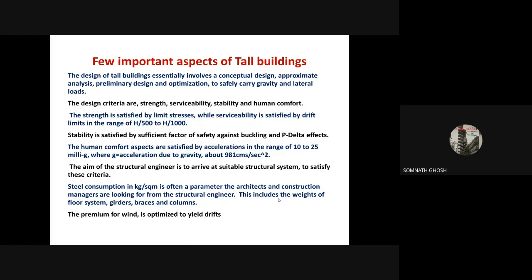So you have to be very careful about this particular aspect. The strength is satisfied by limiting stresses, obviously. Serviceability is satisfied by drift, I already told you. It is normally kept within H/500 to H/1000, depending on the situation. Stability is satisfied by sufficient factor of safety against buckling and P-delta effects. Now, this buckling, P-delta effect, I will be discussing in detail